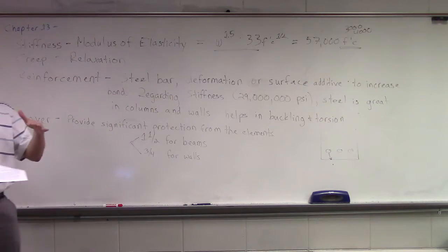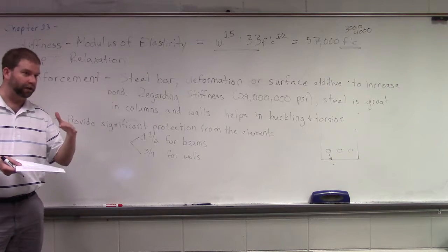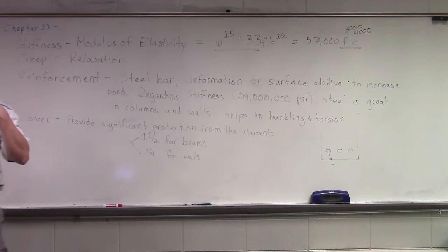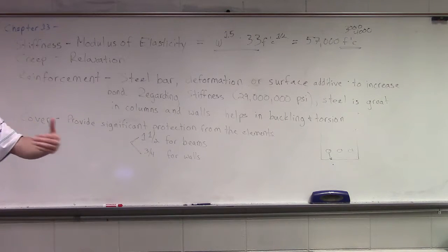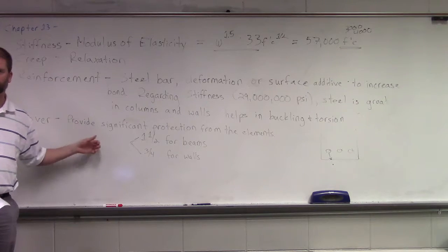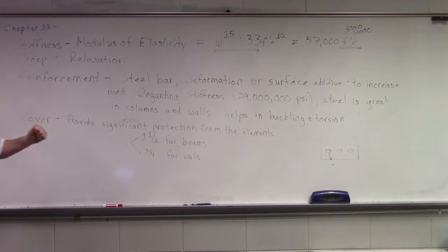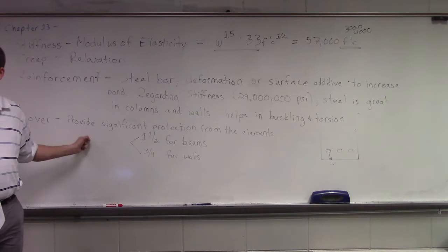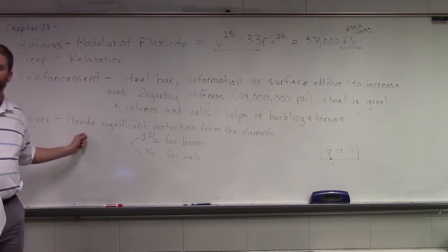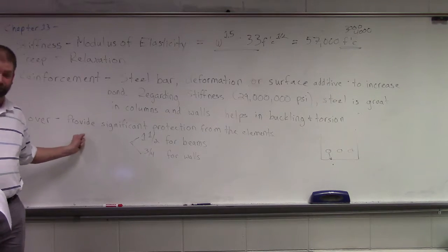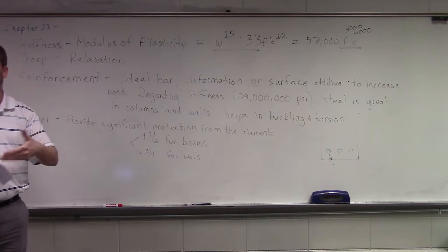It doesn't mean that we just provide that while it's curing. It needs that protection throughout its life cycle. From a life cycle standpoint, we have to be aware of this because remember, what is the steel doing? Predominantly providing tensile reinforcement, right? What do we also know that concrete is always going to do? Always going to crack, right? And the purpose of the steel is not to prevent it from cracking. The purpose of the steel is, if it cracks, don't let that crack cause failure.